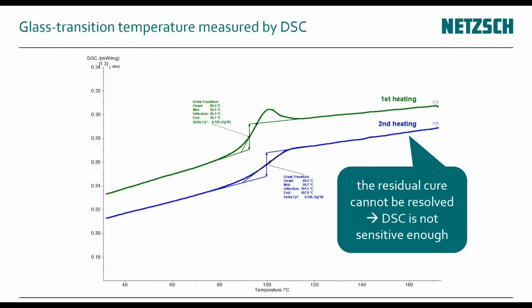If you go back, this is also why I brought the comparison here. This is DSC measurements on the slide, and you can see this step function. It's displayed very nicely, but this is also because we chose the right sample. In real life, this can get really, really hard. You have fiber volume contents of 80% and higher, which just means there's very little polymer left that you can detect in a DSC. And the DSC needs to see the polymer response, of course. So these steps can get very, very small.